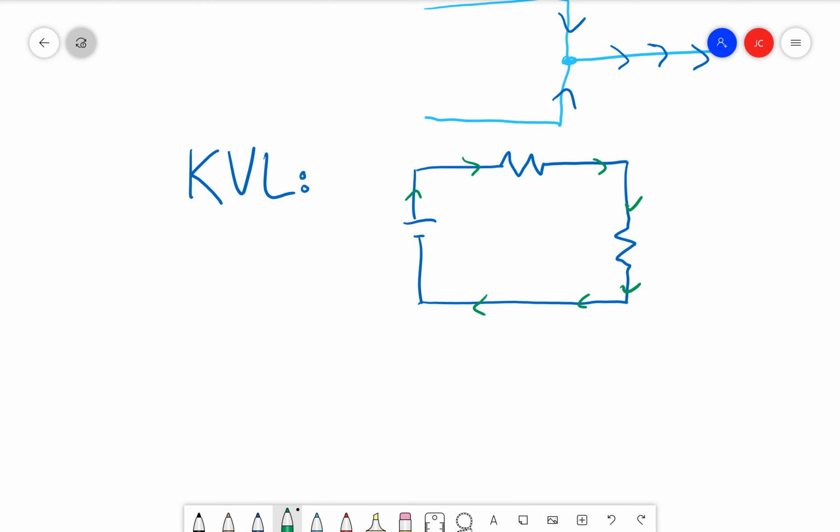So all this is really saying is that if I start with a certain amount of voltage potential difference across this battery, let's say there's a voltmeter here and it's measuring the voltage, that this voltage isn't going anywhere. This circuit, when all is said and done, this loop is not going to lose any of this voltage. The difference between before and after is going to be 0.